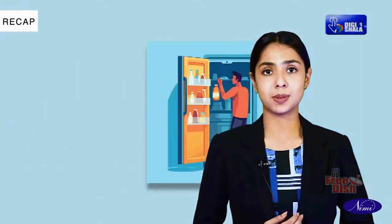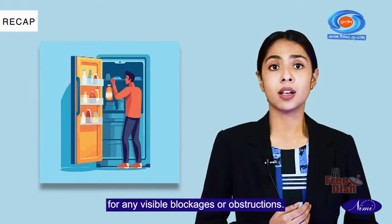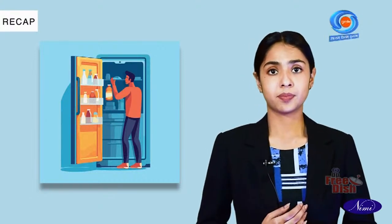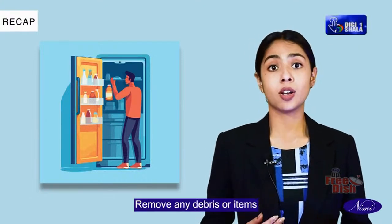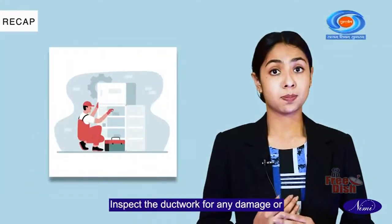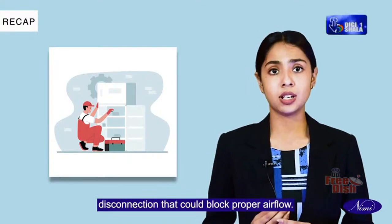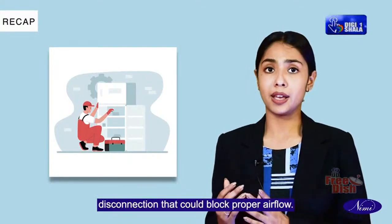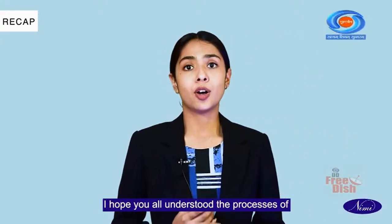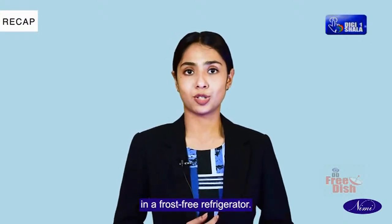Examine the air ducts or vents for any visible blockages or obstructions. Remove any debris or items blocking proper airflow. Inspect the ductwork for any damage or disconnection that could block proper airflow. I hope you all understood the processes of checking the air distribution system in a frost-free refrigerator.